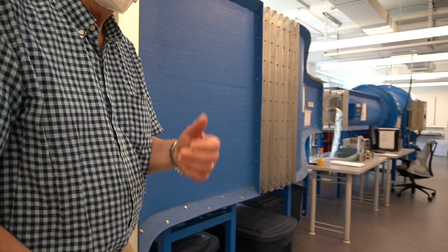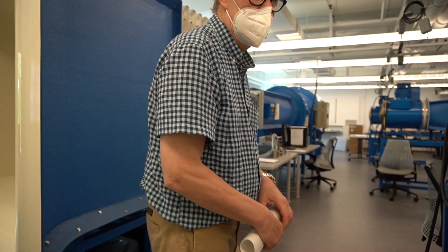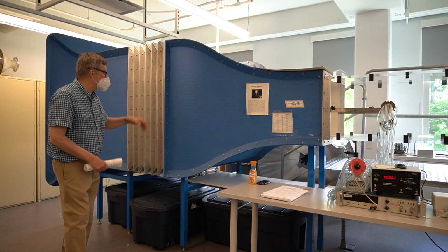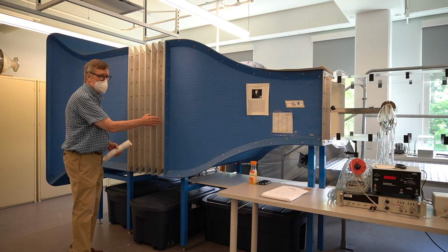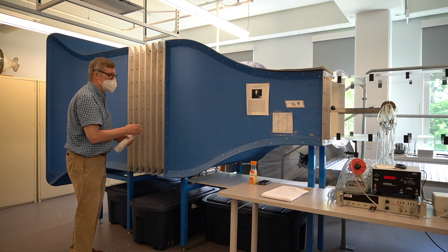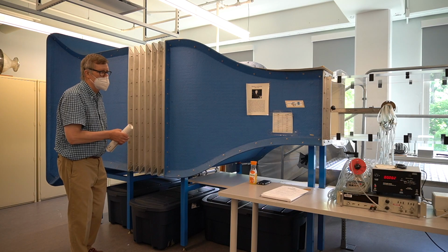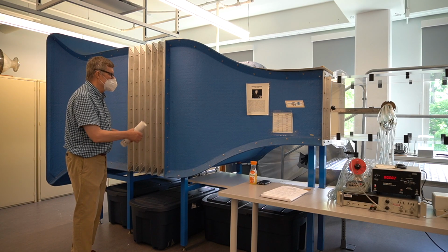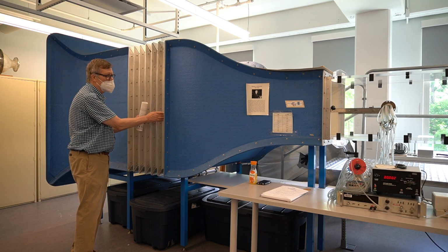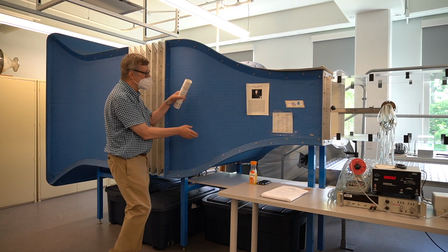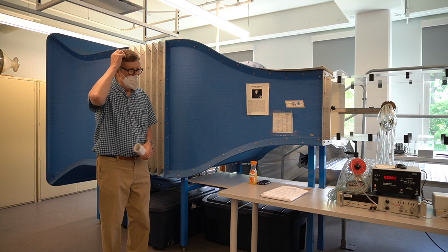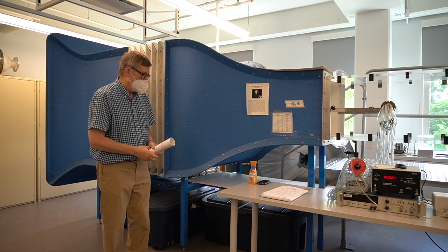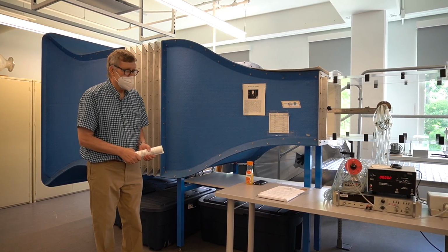Okay, so can I just take you down, take a look at the wind tunnel as we go? These pieces of aluminium here are keeping the honeycombs and screens from getting sucked downstream. So the honeycomb screens are inside here, and then you have a big cross section going to a small cross section, a contraction.